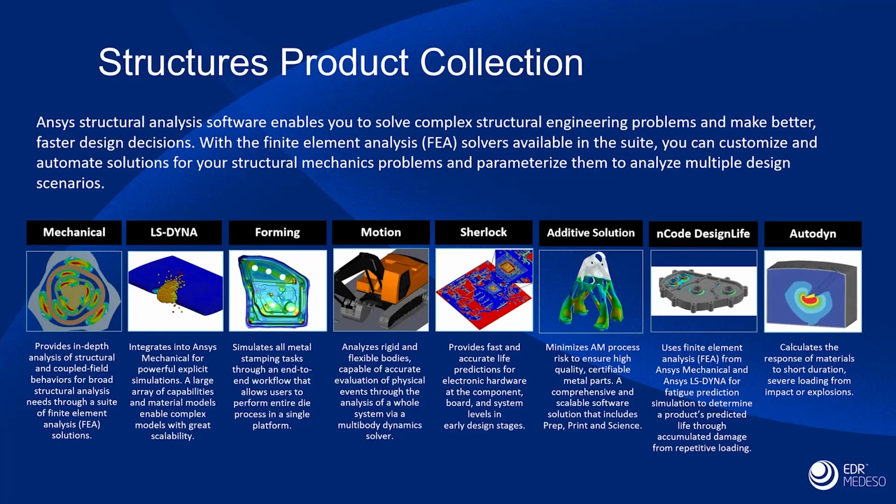Then we've got the explicit solvers, so LS-DYNA and Ansys Explicit, which isn't shown here, it's part of the Ansys suite, and then Autodyn. Now these enable analysis of very highly non-linear scenarios, or events which involve extreme degrees of deformation or significantly changing contact conditions, or which occur over short durations, explosive or hypervelocity events. And then LS-DYNA in particular also offers quite a strong baked-in multiphysics capability with fluid, electromagnetic and thermal solvers baked in.